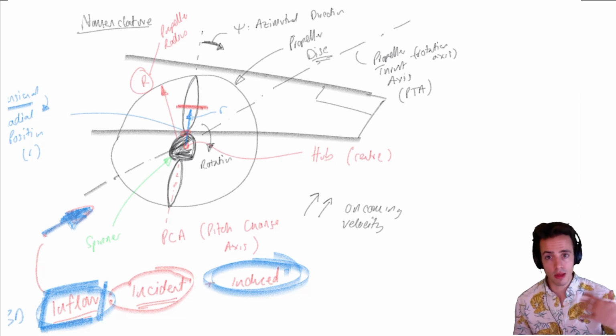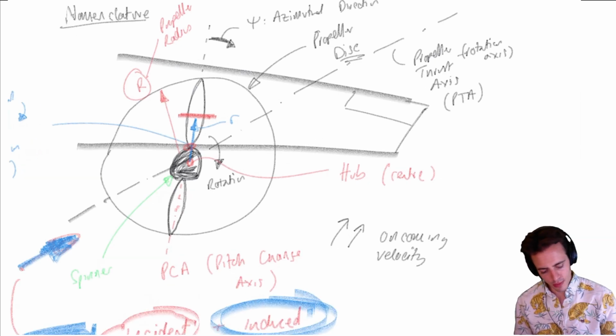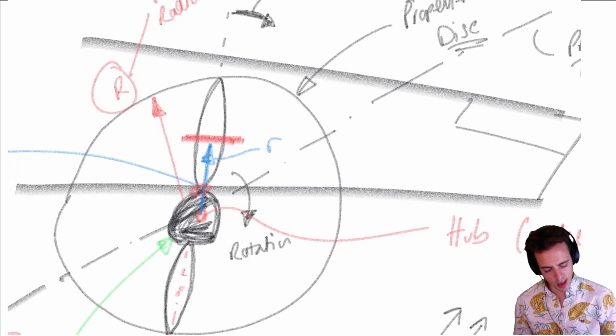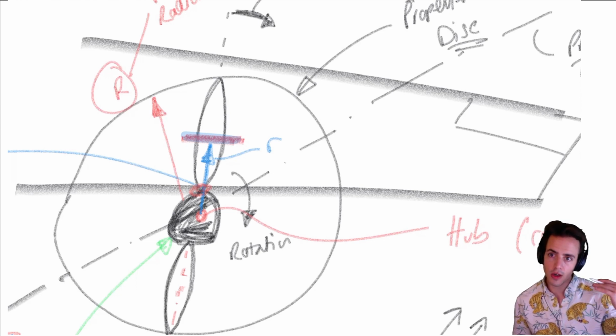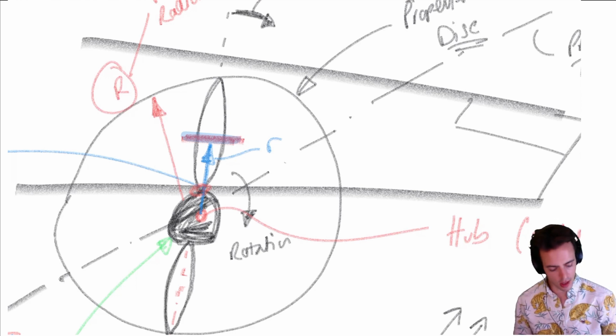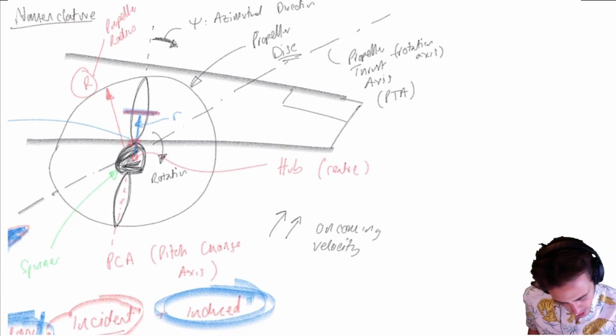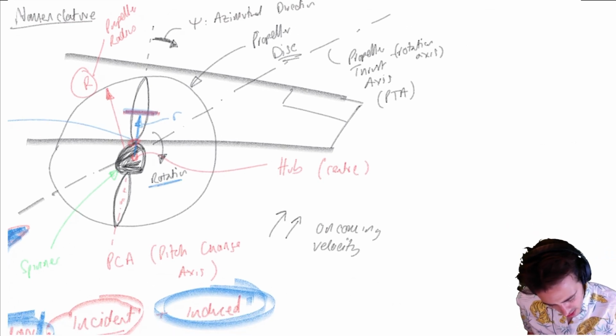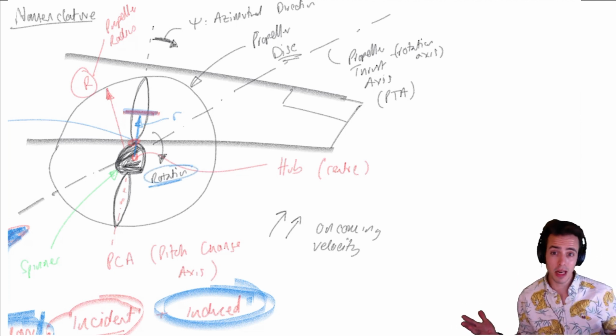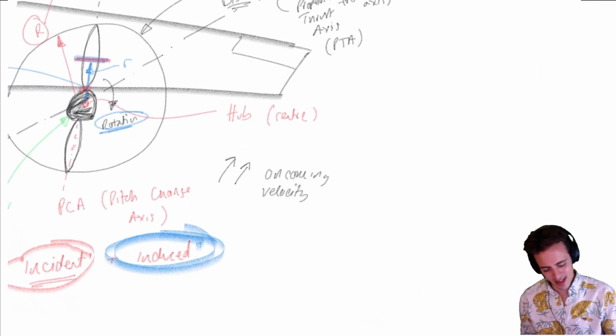So we'll get to momentum theory a little bit later in the week. But for blade element purposes, we're going to say, well, what's occurring in this slice here? We'll take a cross section through there and we'll have a look. Just before we get there, I realise there's one more thing I need to define on here. So we've got rotation. Obviously, rotation is really important. That's how the propellers work. Let's define rotational speed.